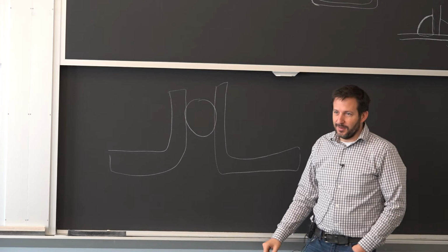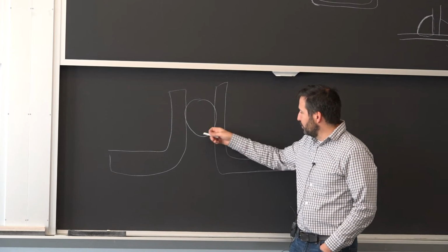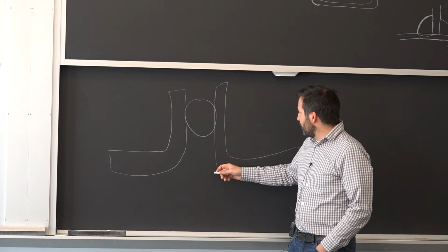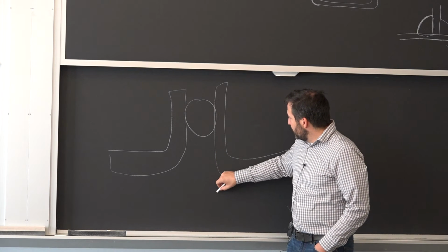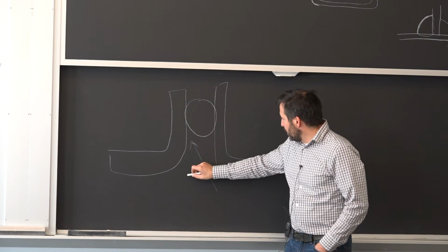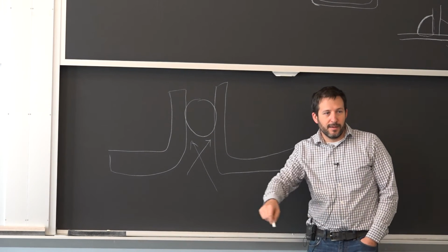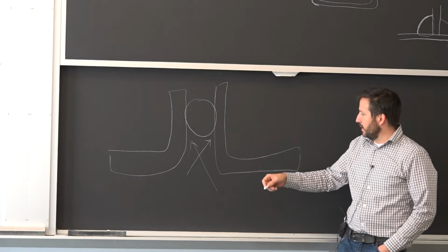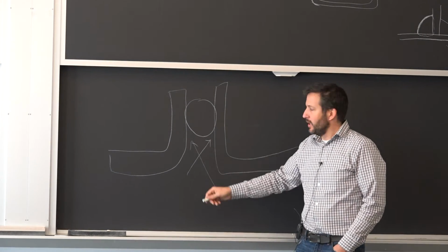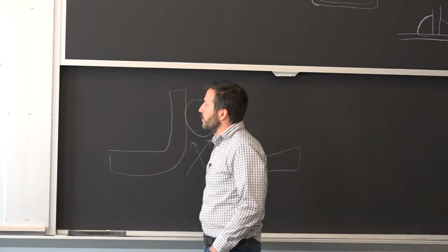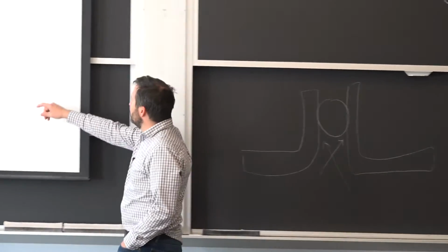Now, somebody very skilled has to come and weld that bar to the other components. A lot of times they'll do it upside down. So they come from here, put a weld there, put a weld there. It's very quick and easy to do, but it's hard access, and again, a slightly different geometry, a flat against a curved surface. And that's what you see here.